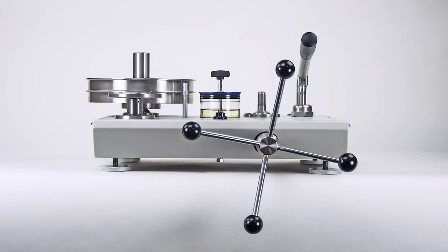When choosing a deadweight tester, one must pay particular attention to the details behind the specifications. Two manufacturers may offer deadweight testers at the same specification, but they may be making different assumptions on how you are going to use it. The P3000 series of deadweight testers can provide 0.015% performance at pressures up to 20,000 psi, even when operated in the simplest way possible. In addition, they can provide even better performance, as good as 0.008%, when further calculations are performed.